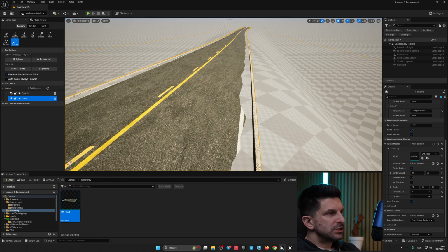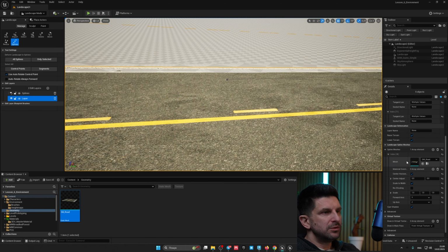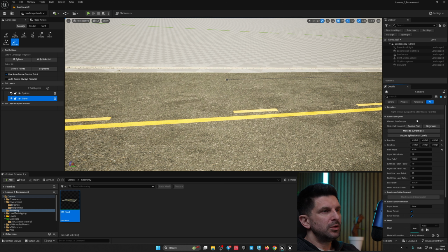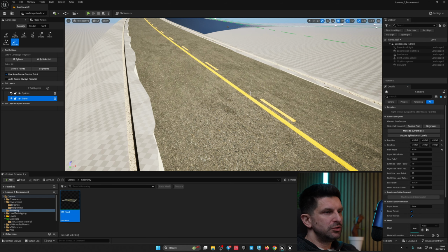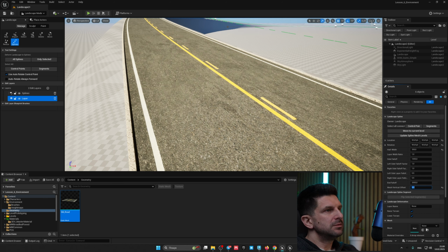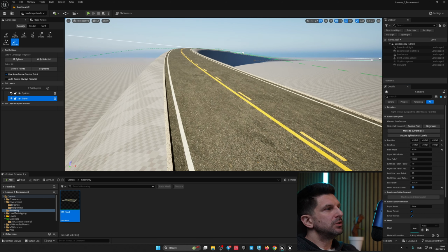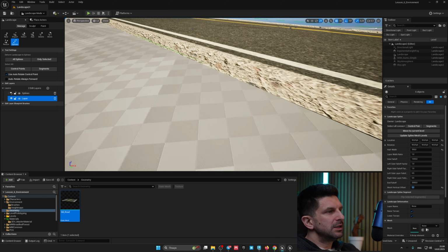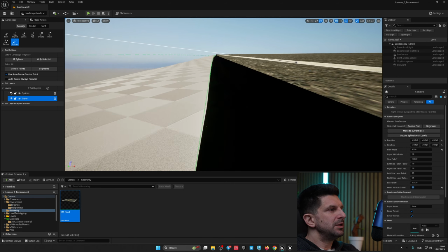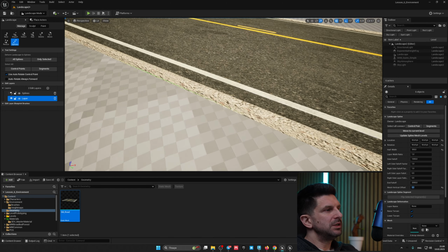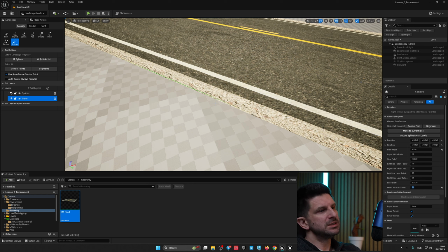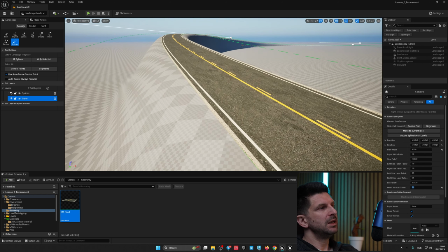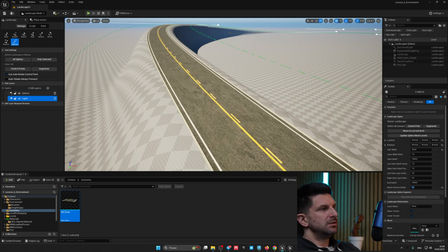If the landscape slightly protrudes, then we have this feature here. When we select the control point, we have the mesh vertical offset here. We can shift our entire road slightly. Let's raise it by 5 centimeters upwards, and that's it. We've raised it. We have a nicely created, neat road. And since we have a curb, we raised those 5 centimeters, and it just covers the side here for us. And it definitely covers this side here. Either there will be grass, or we will fill it with some gravel, stones. So basically there are no problems.